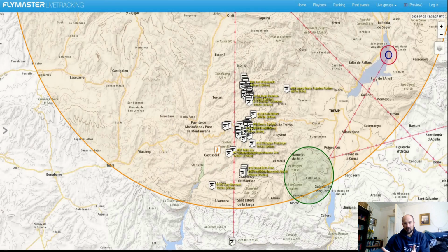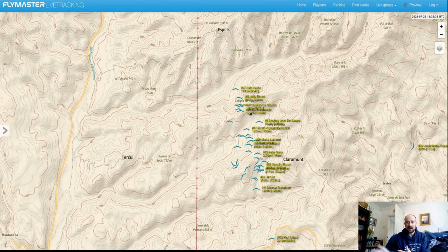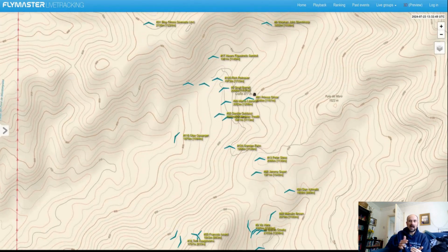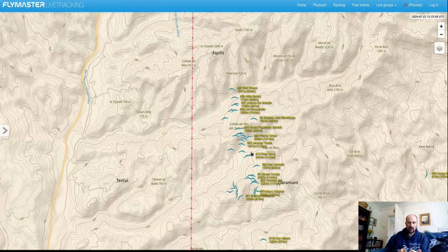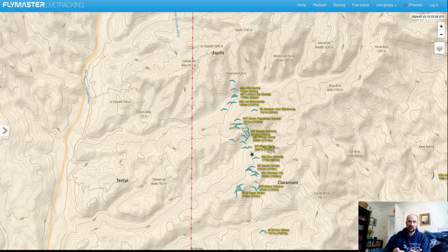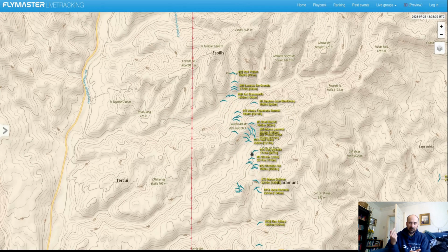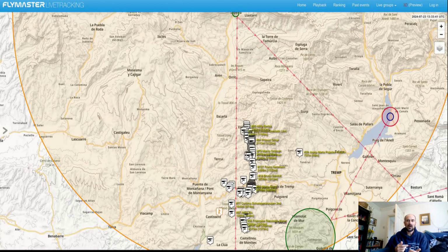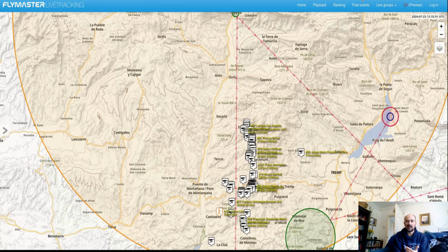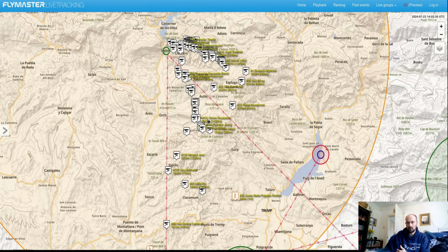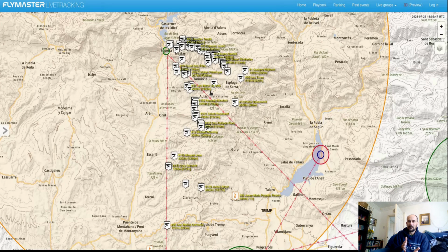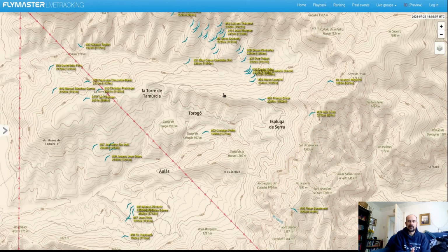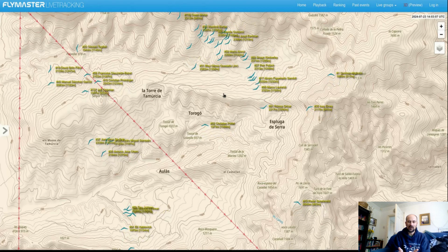Now, of course, I'm not saying parasitic drag doesn't matter. It does matter also, and it really matters when you're starting to glide very fast as well. So in a competition setting, especially on a good day when you can climb very fast and you have to glide very fast, then on those days parasitic drag will be more important. But on a lot of flights, the induced drag is at least as important, if not more important.